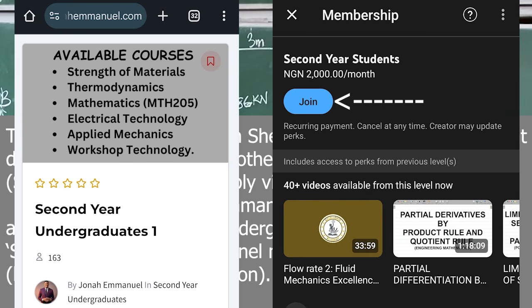Come to x equal to 5 meters. You had two conditions. Condition 1, what was the value? It will be the same place as here, so 2.86 kilonewton. What's condition 2? Minus 27.14. Will it be above or below? It will come down to negative. So I'll come down here. I'll call this minus 27.14 kilonewton. All right, that's this point here.